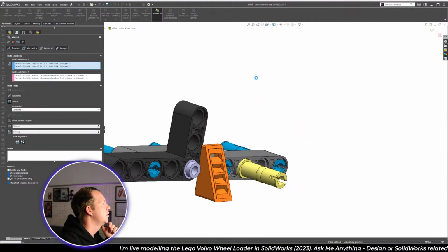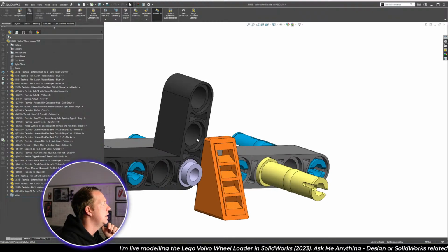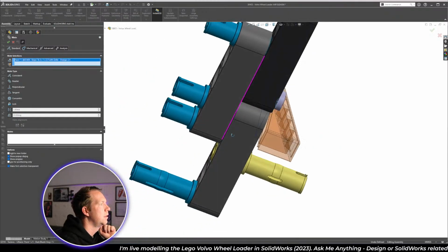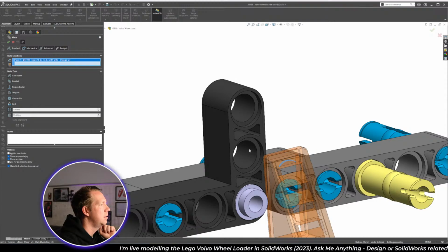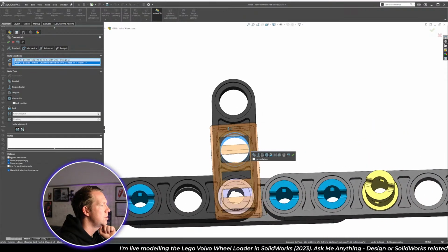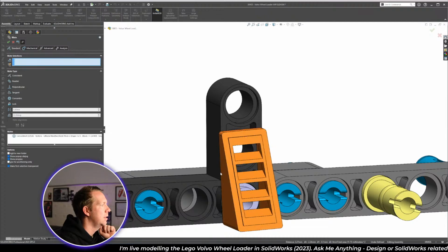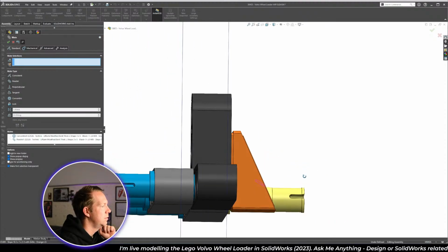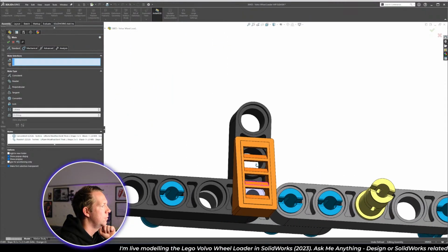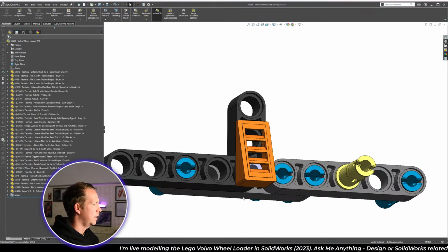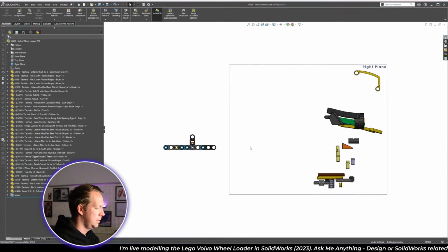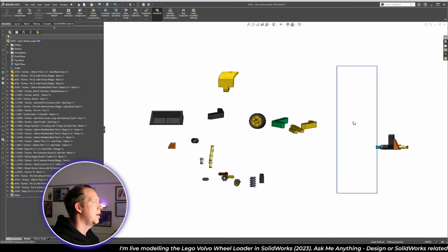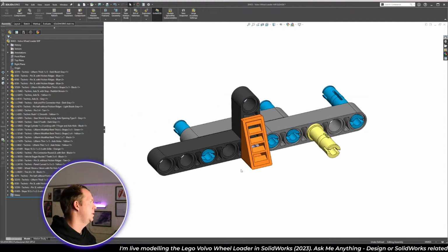The alternative, because it does have that cut in it, if I can just see up here, this one, I can align that hole with this one. It's going to be concentric. And then I can press this face and this face to make them parallel. That should work as well. We'll have to check later. It looks like maybe it sits a little bit low. And see here. So we might have to tweak it. We'll see if there's any interference.